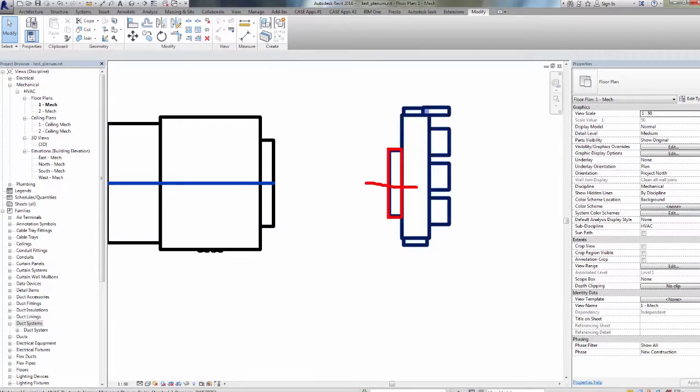Since this is not the case, we are aligning the floor with the plenum neck. The plenum is getting adjusted always taking the neck as a reference, so the neck is not getting displaced. The plenum will only move when its dimensions or connector types are modified.